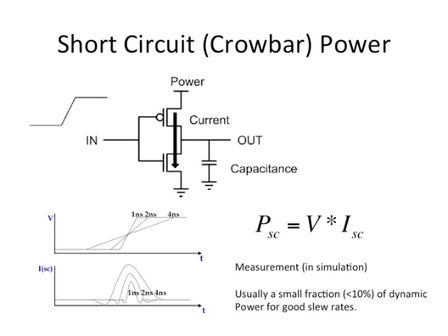In general, a lot of times it helps to look at the extreme conditions to get a sense for what is happening. Then you can understand what is happening in between. So here the extreme is when you have an ideal step, and you see that the peak is 0, so it has to change in between. So it means that the short circuit current is dependent on the load. Short circuit current also depends on the load, absolutely. So it's a function of both the input ramp rate as well as the output ramp rate, and the output ramp rate depends on the load.